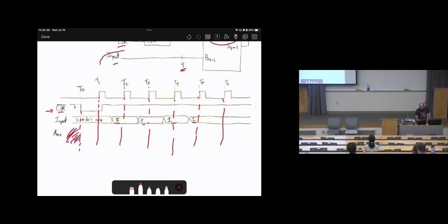Then the clear button has been pressed. Since the clear button has been pressed, this will make the output 0. We don't care what's at the input because the clear button has been pressed. Whatever money was in that machine before, I don't need to worry about it because I removed it and then pressed the clear button. After releasing the clear button, the first update happens here.